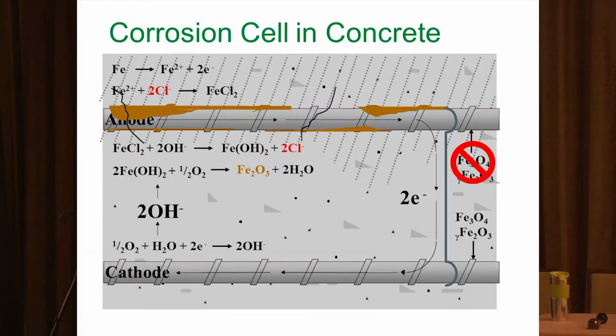The next thing that's going to happen is that you start to form some of these same things that we were talking about before with the typical battery. The top steel becomes an anode, the bottom steel becomes a cathode, and what you'll recognize here is those same battery components. The only thing you need is the ionic transfer. And when you have the ionic transfer, which is basically through the concrete, you have the next culprit, the next domino to fall, so to speak, and that's ferric oxide.